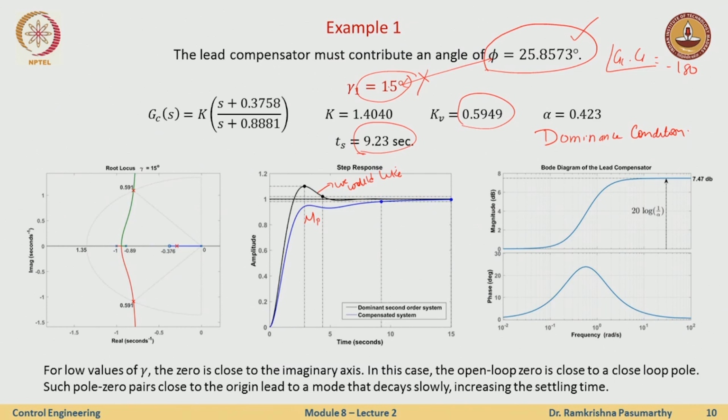Okay. So why is this happening? Why is the dominance condition failing? Because very close to the closed loop poles is a 0, right, and that is here. So if you look at this guy, how did we define the dominant poles? That they should be here, such that there is nobody sitting over here and the other guy should be further away from some limit. But here, there is this 0 here, which helps losing the dominance, right.